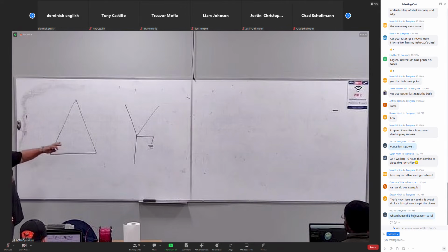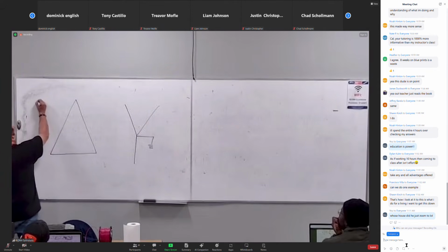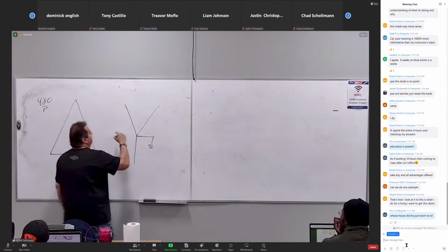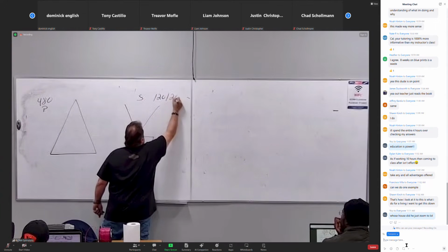Every delta Y problem that you're going to see on your test, on your quiz, on your things, if you draw out what I tell you to do right here every single time, you cannot get it wrong. This doesn't lie. There's no mystery here. There's no trick. This transformer is gonna be a 3-phase transformer. It's gonna have a 480 volt primary. It's primary, okay? My secondary is gonna be 120/208. Okay?